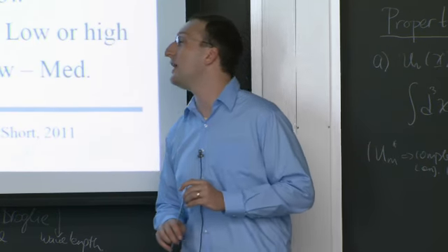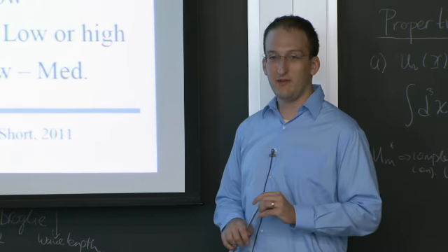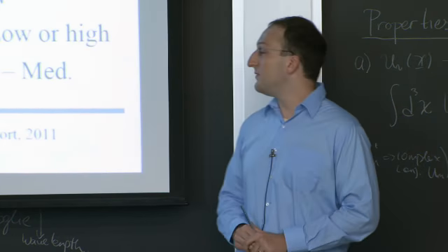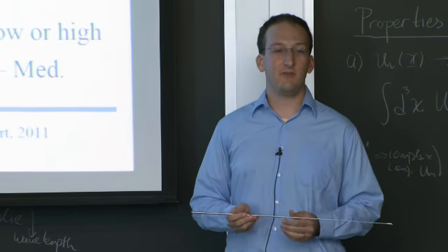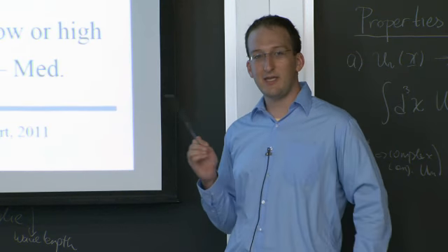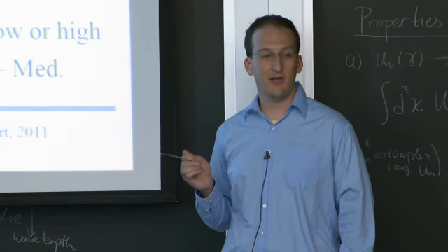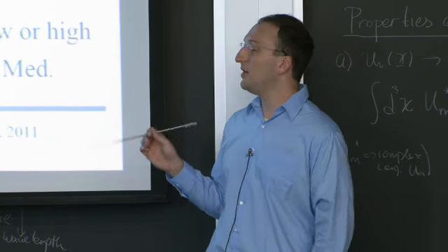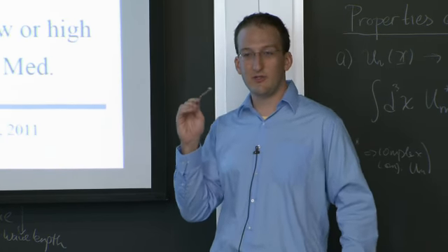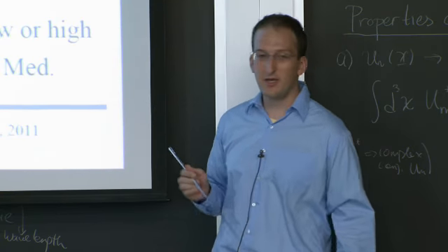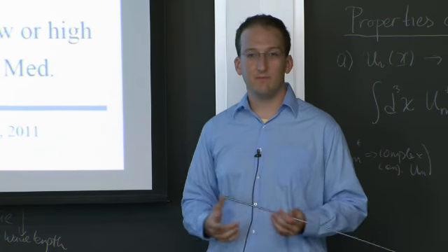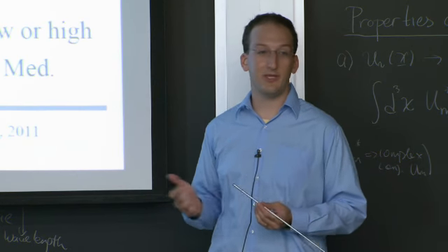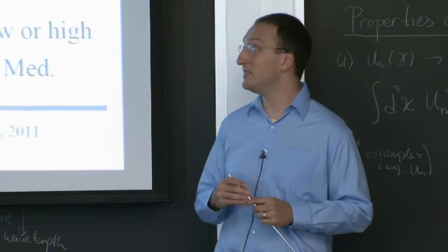And then there's the very high temperature reactor. It runs at a very high temperature. They've been saying 1,000, 1,100 degrees Celsius. That may have to be downgraded a little bit, 950, 900. If you guys look at the history of designs claiming VHTR parameters, the outlet temperatures are sort of creeping down, because not a lot of metals can hold up pretty well in terms of corrosion, in terms of just holding up their own weight at 1,100 C.